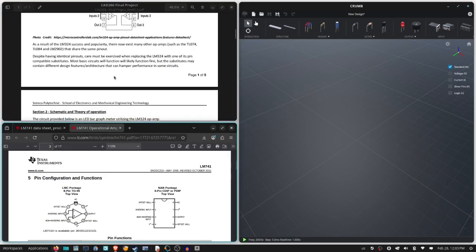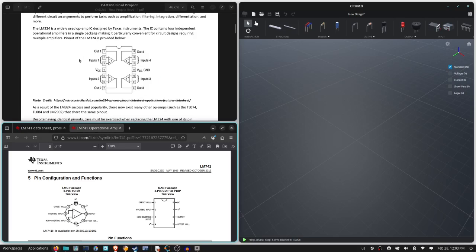So we have our op amp here, and we get two inputs for each op amp, right? We have our non-inverting input and our inverting input here. So 3 is non-inverting, that's plus. 2 is inverting, and we're putting our reference voltage on the inverting input of each op amp.